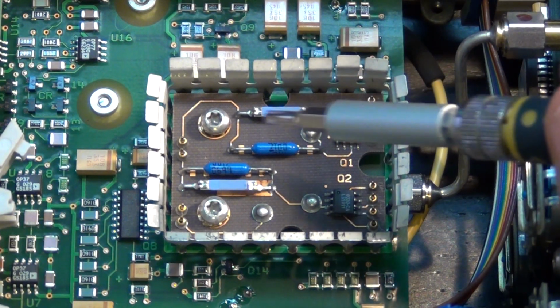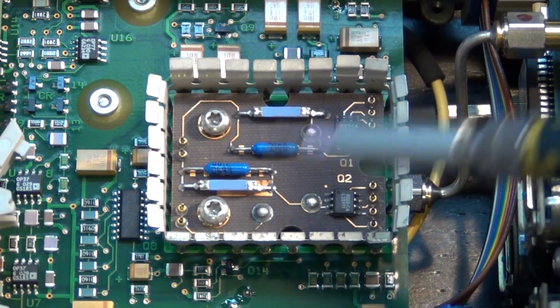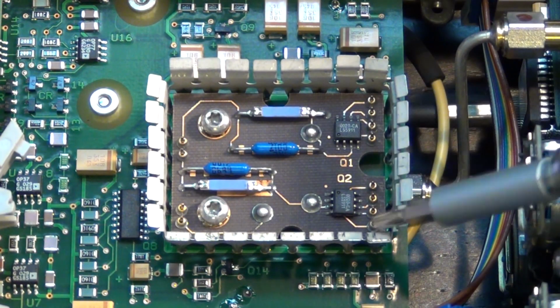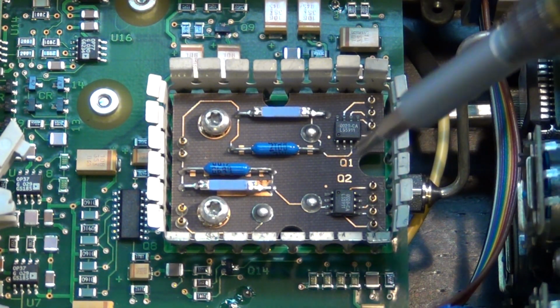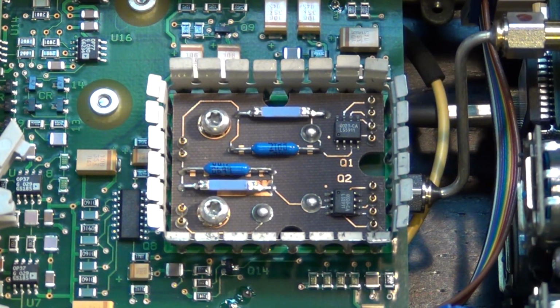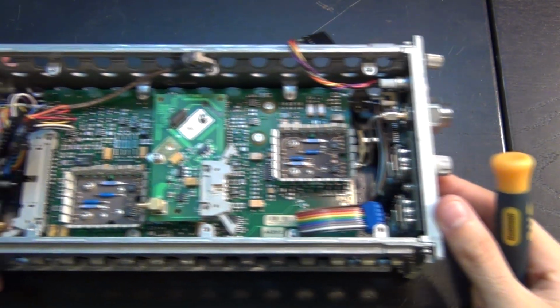And there's some other components here which are either responsible for filtering, and I can't quite figure out exactly what's going on because I don't know what the pin interfaces are to the module which go onto the board to the other side, but either some filtering on the power supply or these are in negative feedback configuration. But either way, the purpose is very clear: ultra low noise amplification, preserving the dynamic range of the IF signal coming out. So pretty nice and clean design on that.